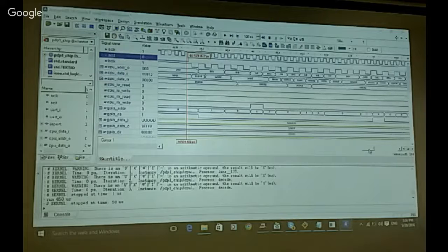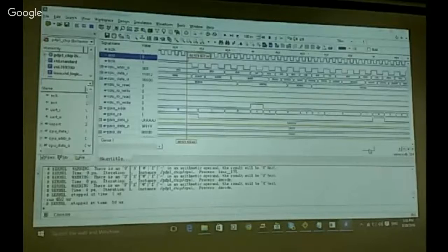Okay, but you can simulate memory by imposing the instructions on the data bus, data input. So you just keep the same data while the clock is running. This forces the CPU to execute the same instruction repeatedly.